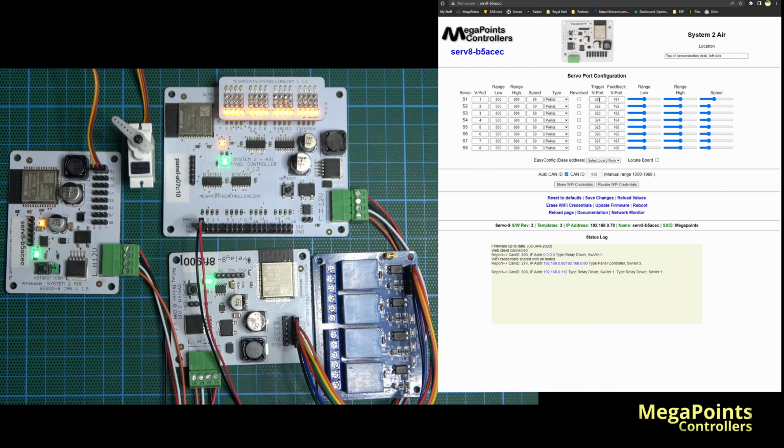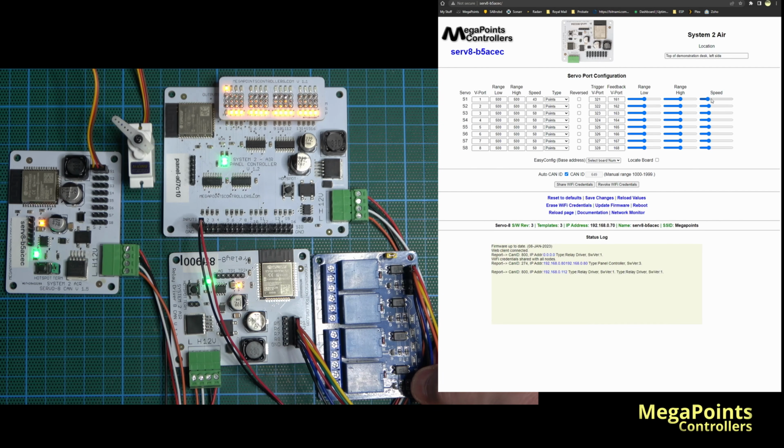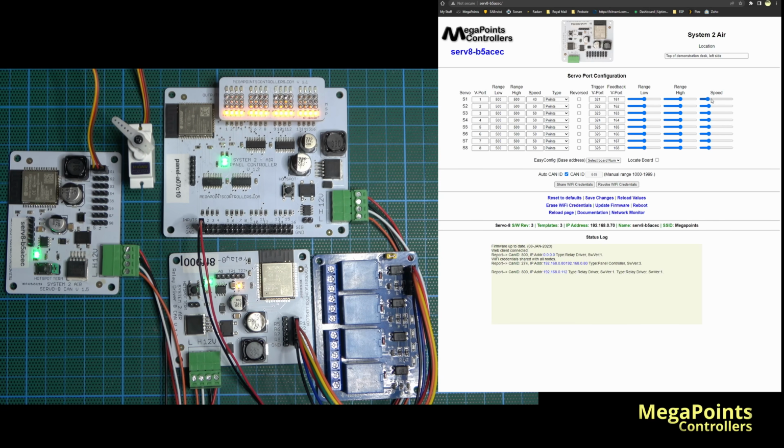And that's so that as your point blades are moving, and this would be particularly of interest to N-gauge modelers, then the polarity changes and avoids a short circuit. If I bring the speed right down, you perhaps see it a little bit clearer. As the servo gets to the center, it throws it. And then as it goes back, it doesn't. Now, if I didn't want this flashing light on my panel, then I can put it back on.